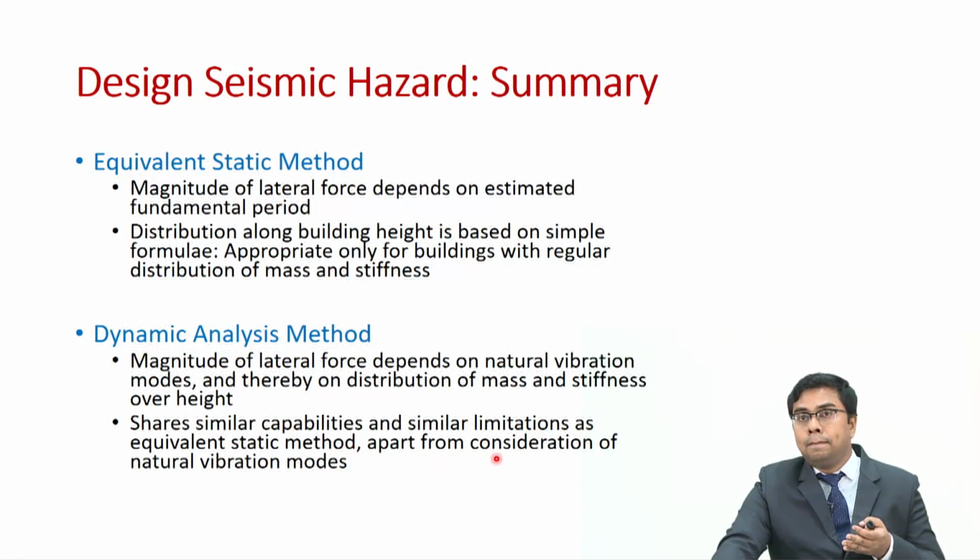However, there is a slight difference: the dynamic analysis method is able to capture various natural vibration modes. However, the equivalent static method ignores any other natural vibration mode. It gives just a fundamental natural period.